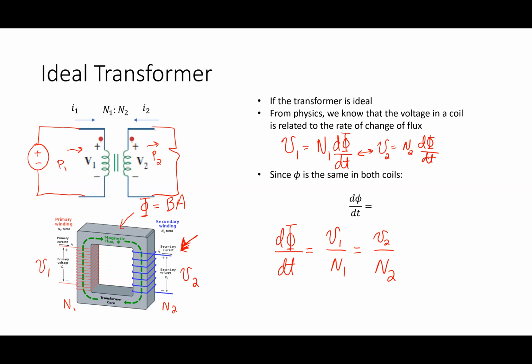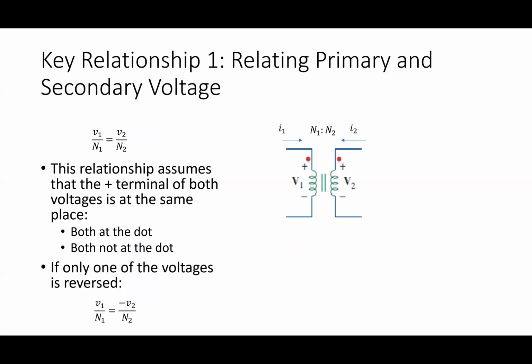So power is what times what? V times I. That's our definition of power, V times I. In a resistor, it becomes I squared R, because of Ohm's law, but the definition of power is V times I, right? So in this case, if the voltage goes up, the current should go down. V times I on one side, V times I on the other side. If voltage is higher, current better be lower, okay? So we can figure that out.